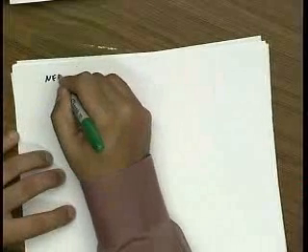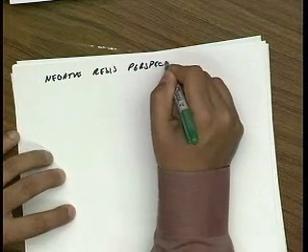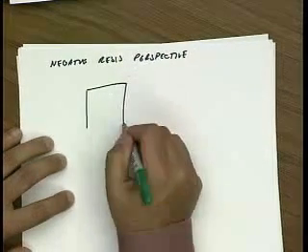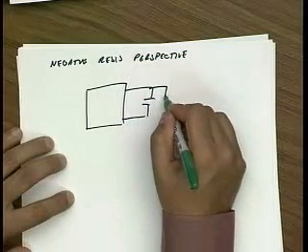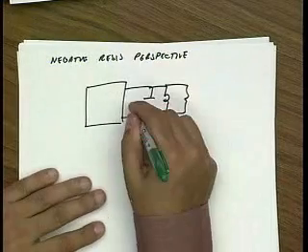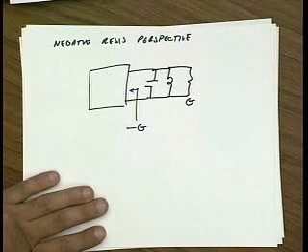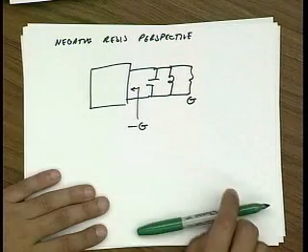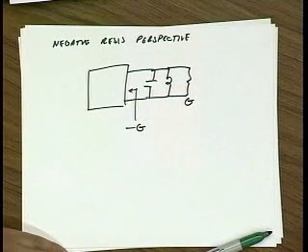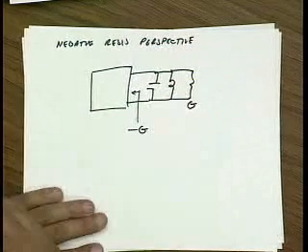So the question is, remember, that we can analyze our oscillator as a lossy LC tank, say with conductance G, and a circuit that somehow or another creates a conductance minus G. And this is consistent with our energy balance perspective, because if this circuit is supplying energy, that means it has negative resistance, right?